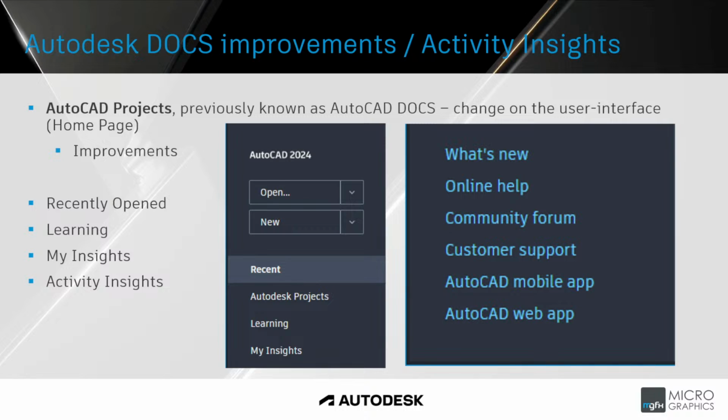To move between layouts, create a layout from a template, publish layouts, and more, use the New Layout tab menu. Right-click a layout name to see more options. Use Ctrl or Shift to select multiple layout names from the menu. Ensure you are using the most recent desktop connector when accessing files from Autodesk Docs.